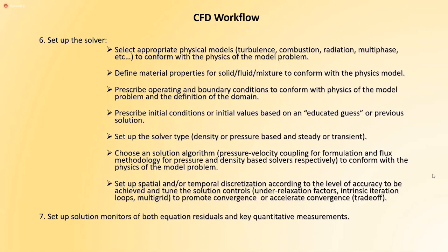There are many kinds of initializations, and this could mean not only more time, but the difference between diverging or converging. With previous solutions, sometimes you'd like to take a scale adaptive simulation and use it as a basis for a large eddy simulation or stuff like that. Set up the solver: density or pressure based, and steady or transient.